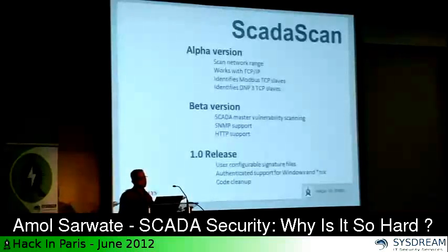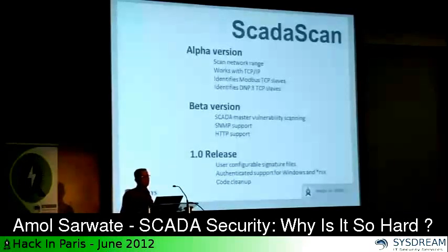So this is basically the SCADA scan tool that I was talking about. It's currently even pre-beta, I call it alpha version. It scans a network range, works on TCP/IP, and identifies Modbus, DNP3. But the fun will start a few months down the road, when it will start supporting SCADA master vulnerabilities, SNMP support. And in the final release, what we plan to do is have user configurable signatures, because no matter